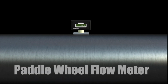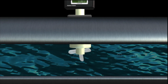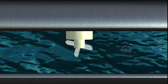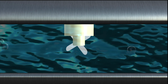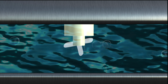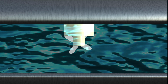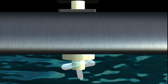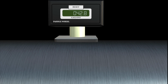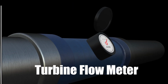Paddle wheel flow meters are mechanical flow meters and are easy to install and operate, resulting in a very low overall cost. The paddle wheel rotates as the water flows through the meter. The rotational speed of the paddle wheel is proportional to the velocity of the water and is used to calculate the flow. The majority of paddle wheel flow meters currently in use are a saddle-mounted configuration. These are commonly installed on small drinking water systems.